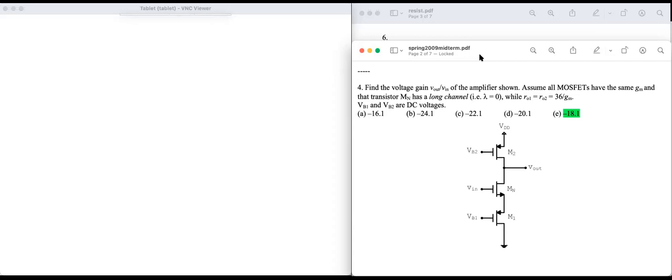But the source of the N MOSFET, MN, is not grounded. The source here is not at signal ground. So there's something between the source and the ground, which is M1. So it's like a common source with a resistor between source and ground. But it's not a regular resistor, it's a MOSFET. And then we have M2 between the drain of MN and the supply.